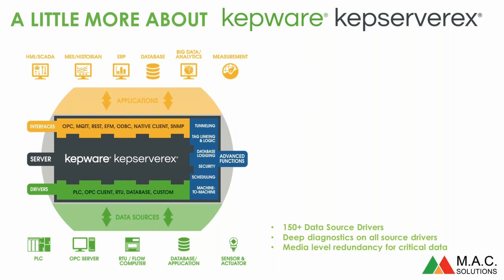For many of the drivers as well, you can put media level redundancy, which means that if you have a PLC which has got dual Ethernet cards or perhaps dual CPUs, you can actually get KEPServer to connect to that PLC using path A and path B, and be able to switch seamlessly between those two paths should one of the paths disappear. So if you have a critical PLC which has that type of dual infrastructure, you can make Kepware have that dual approach as well, one level above.